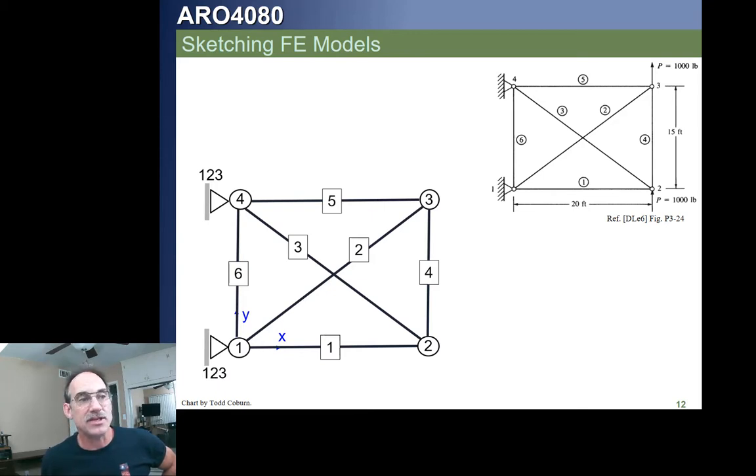Now, while this is only a planar problem, NASTRAN will tend to have singular results if you don't constrain the model in all degrees of freedom. So if there's no element to provide stiffness out of plane, your model will generally crash. So what we will often do is put a constraint to keep it from moving in the out of plane direction, even though there are no forces applied in that direction. It won't affect anything. It'll be like sliding on a frictionless surface. If all of the loading is in the plane, then there will be no reason for it to move out of plane, so putting a constraint in the out of plane direction will just allow the purging of those degrees of freedom so your NASTRAN model doesn't blow up.